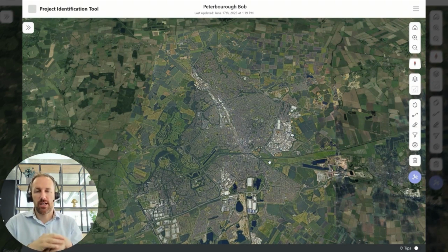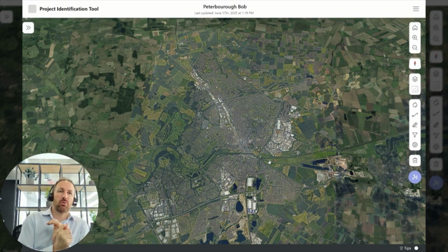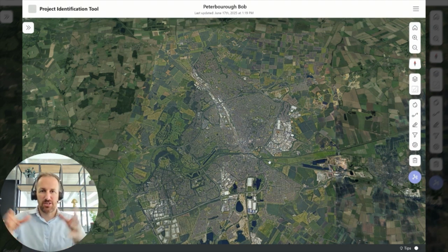If you're generating the heat from scratch using heat pumps, air source heat pumps, it works, but it's not the cheapest way of doing it. Ideally for heat networks, you want a waste source of heat. So industrial waste heat is great. If you've got a power station that's churning out heat, so think of the big chimneys you're used to seeing around your cities. If someone's got a big chimney, chances are they've got some waste heat somewhere. So it's about tapping into those resources.